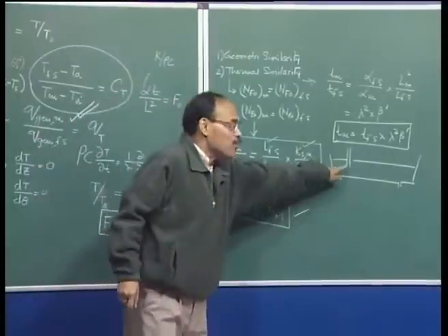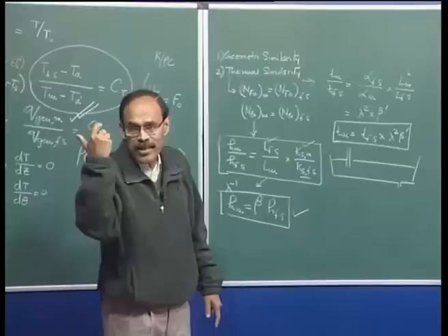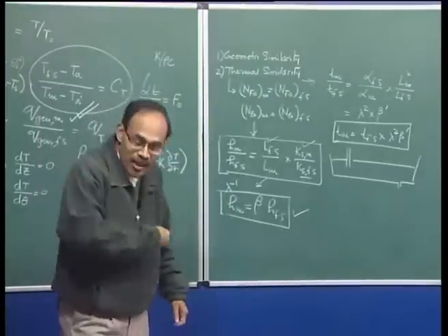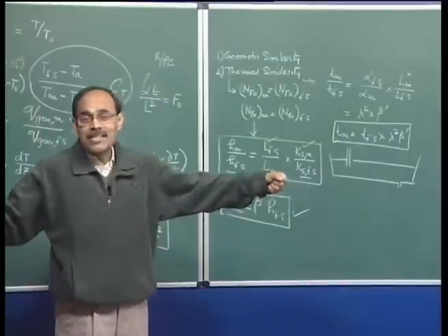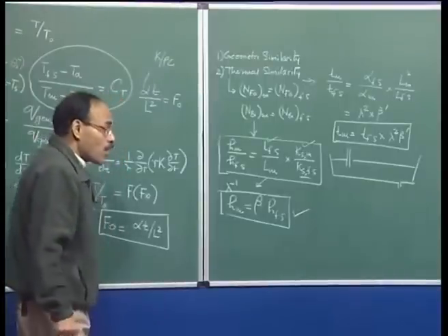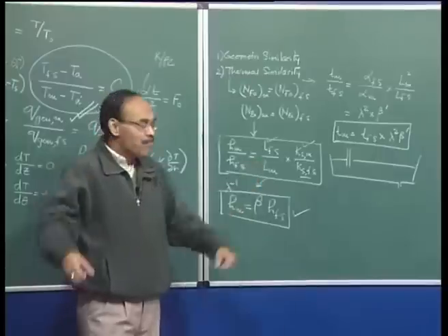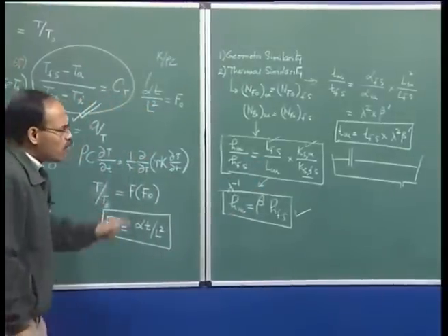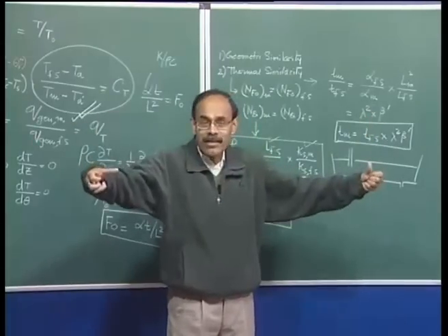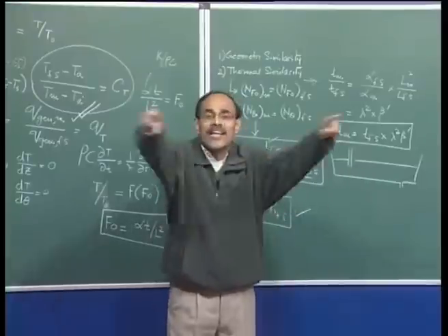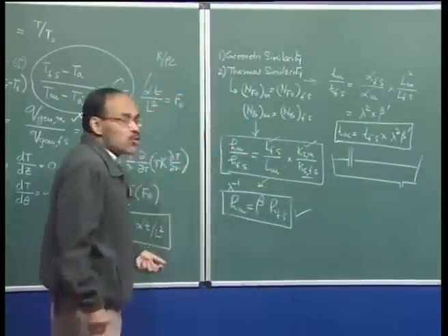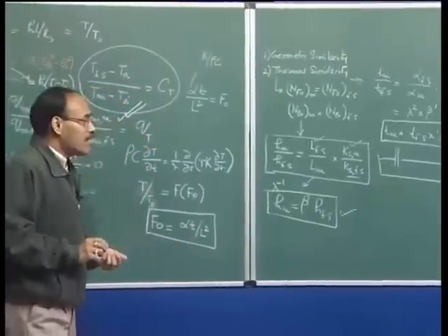Now, water I can only use up to 100 degree centigrade or 95 degree centigrade, and at 95 degree centigrade, if I use a glass vessel, the rate at which the heat will be lost, that similarity I will not be able to maintain with the actual steel making system on the shop floor, because there the rate of heat flow is going to be significantly larger. So, it will be very difficult for us to maintain the similarity of heat loss behavior in a laboratory scale system by using a glass vessel of ladle or tun dish or mold, etc. So, thermal similarity studies are going to be really difficult.